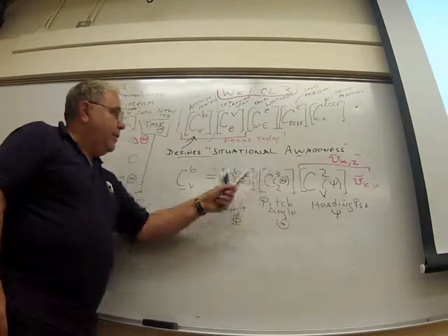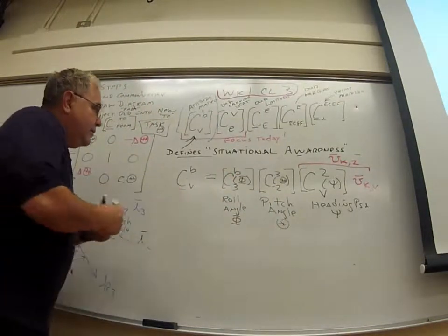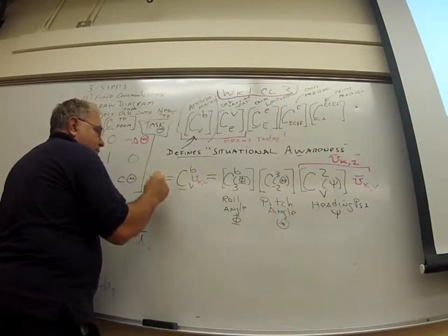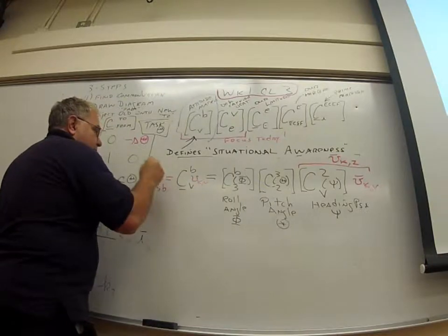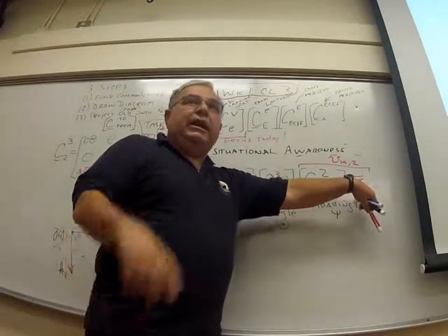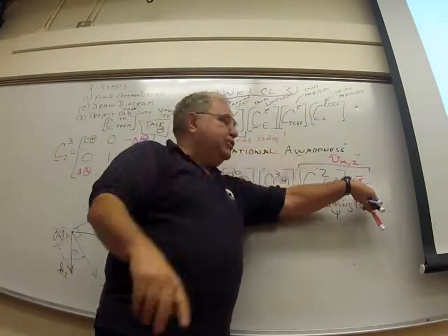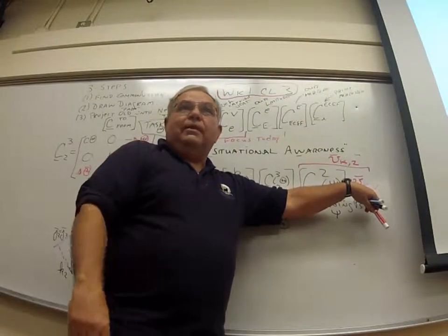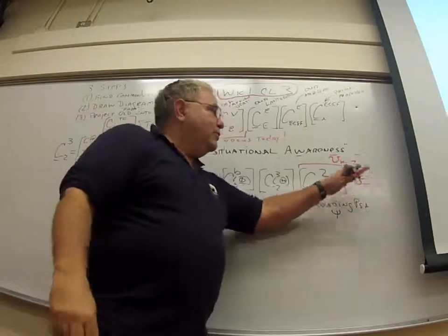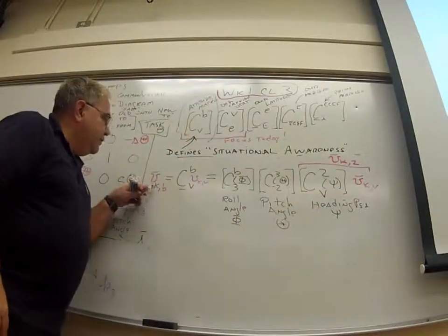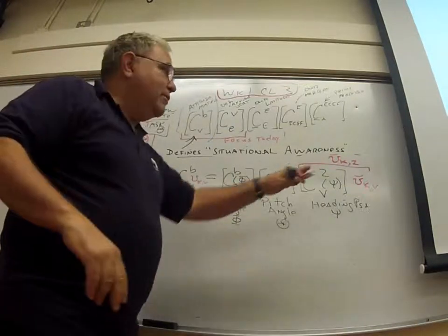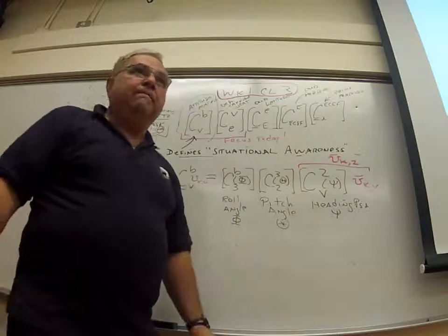And when I take VK, comma, 3 and put it here, I'm going to get VK, comma, B. So if God looked down on my airplane and saw me going at this speed in the VK, northeast down, and I wanted to know my indicated airspeed, the wind in the face, I would run through this coordinate transformation, and that would give me my wind in the face. So I could transform the velocity vector from any coordinate frame I want using this product.